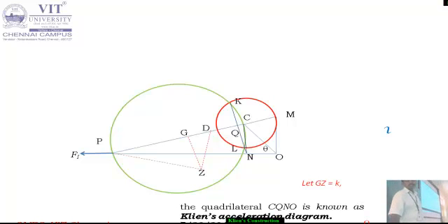So for that what you have to do? From G, extend one line parallel to the line of stroke till the resultant, that is the small g. From D, draw one line parallel to the line of stroke until that resultant, that is your small d. Okay, so now join OG and OD. That gives you the small vector, OG vector and OD vector. So that gives you the acceleration of G or acceleration of D with respect to the fixed point.